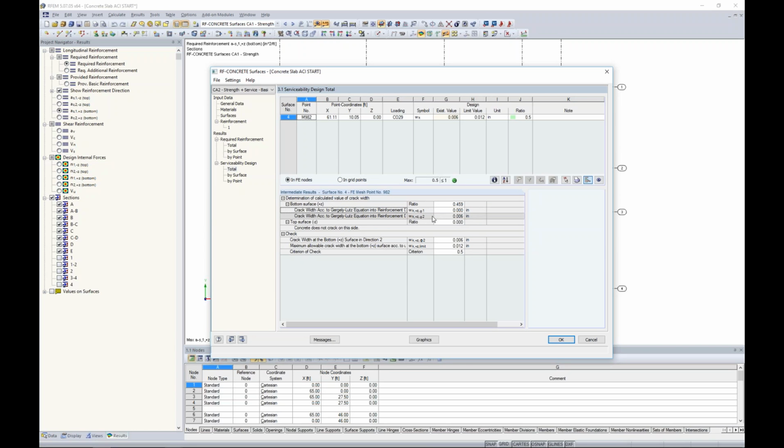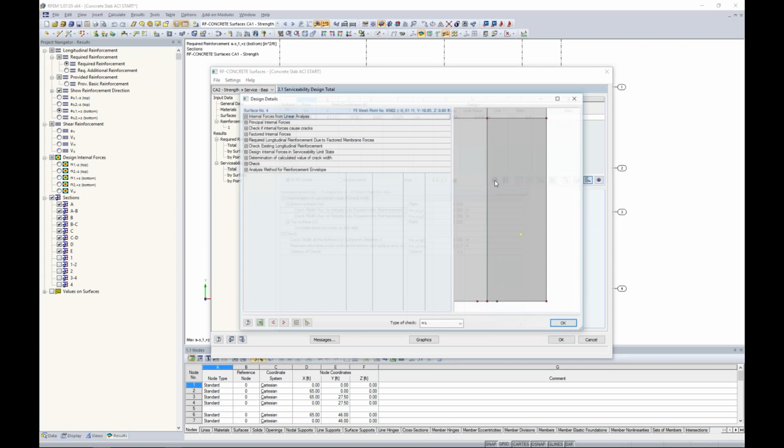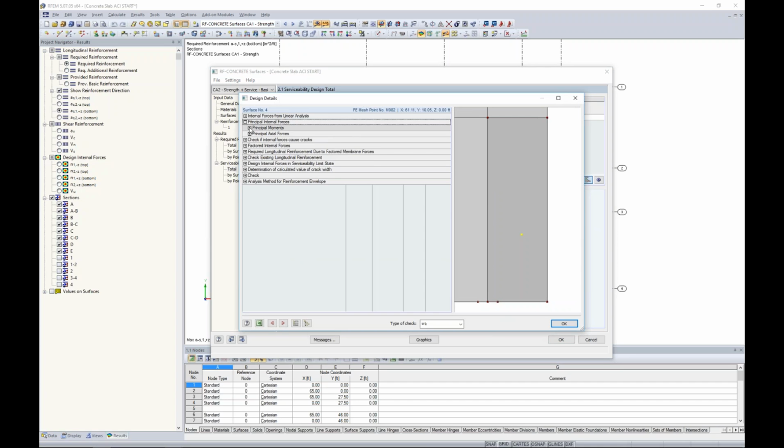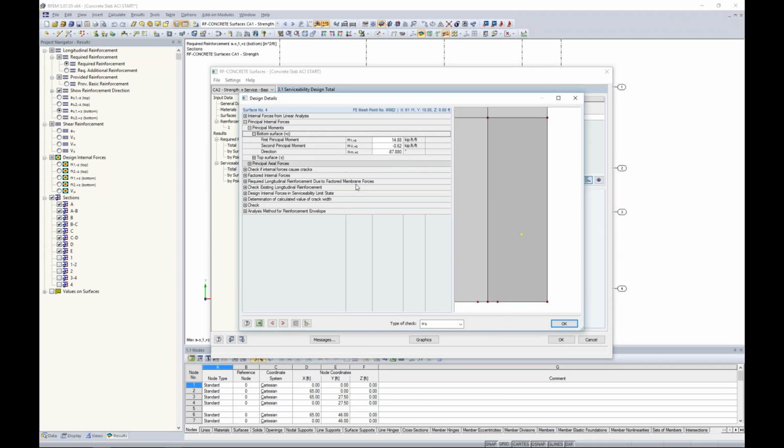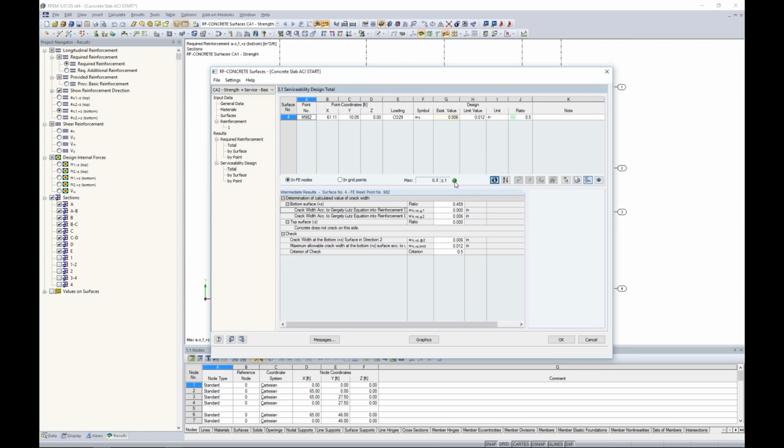We're actually calculating a specific crack width. We're also meeting the allowable spacings according to the code that we set in the limiting factors as well. Again, you can press this info button to get all of the possible information that you need and which location you're looking at exactly for how those calculations were derived.